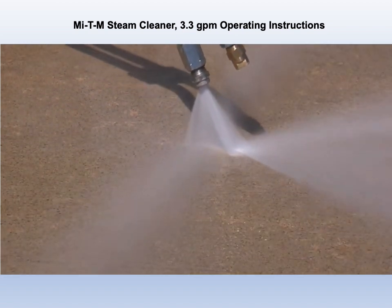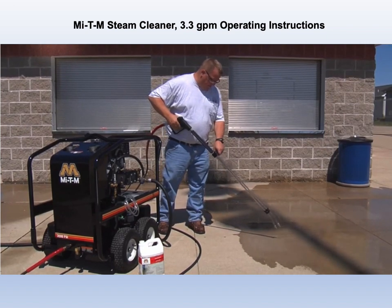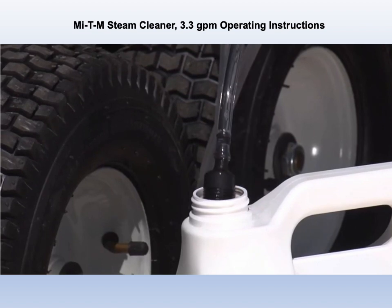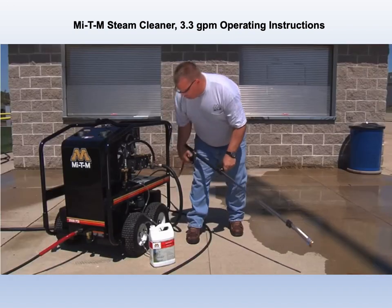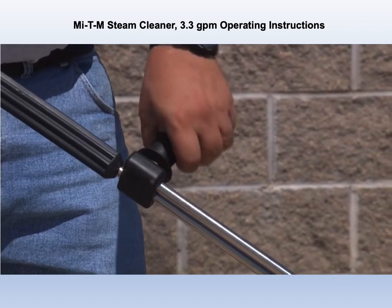For even greater cleaning power, use detergent that is specifically developed for use with your hot water pressure washer. First, put the detergent hose into the detergent container and open the detergent valve on the pressure washer. To begin drawing detergent, you must open the handle on the dual lance wand by turning it clockwise.